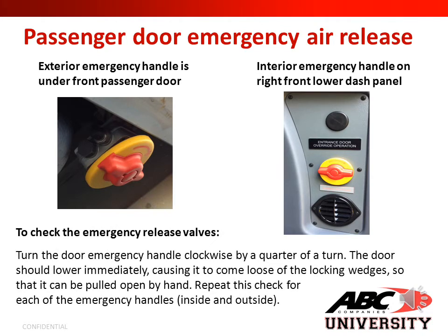Checking your passenger door emergency air release. First, you have your exterior emergency air handle under the front passenger door. Your interior emergency handle is on the right front lower dash panel. And this could vary by coach.